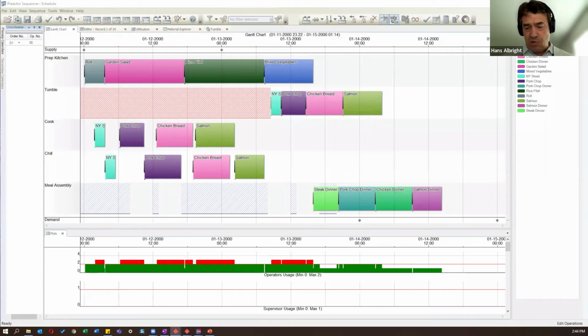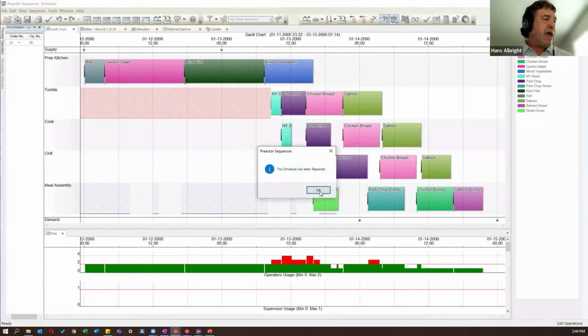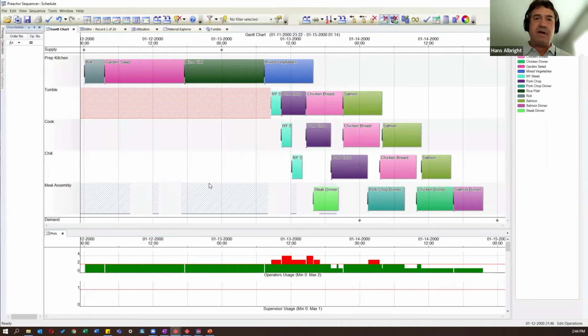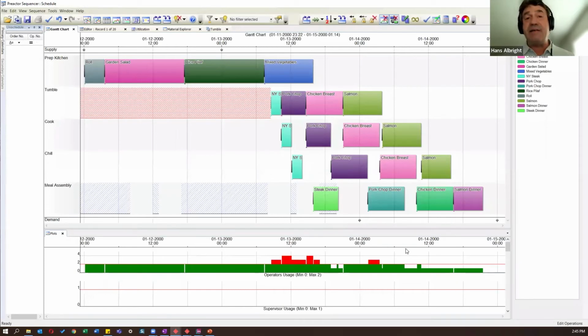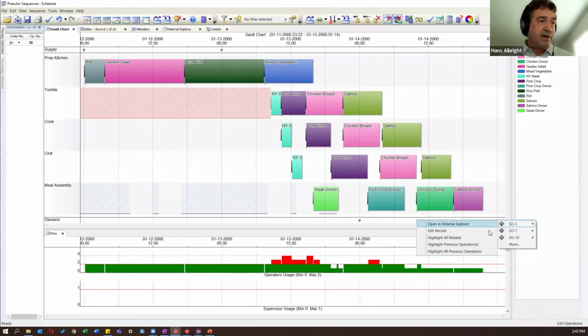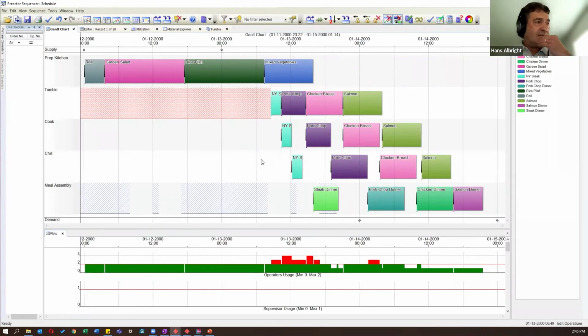So this is where we have a tool called the Repair Schedule tool. And what that does is correct those types of inconsistencies, things that are out of sync, and so forth. So by using that tool, I was able to effectively push all of the jobs beyond that non-working period where the machine is down, and then it just picks up the flow from there for everything. Now, at this point, we're lucky because it hasn't made anything late yet. Everything here is still on time because we have our sales orders down here and our sales order dates, so we're good there.